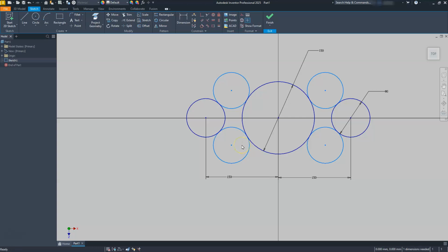Okay, finally, I can use my trim, so just a T. I'm sorry, it's X actually in this command. So I can use the X, and that'll put me into the trim mode, or select the icon that is located here. And then the last thing I need to do is go ahead and put a radius on here. So I'll go to my dimension, select here, and this has a radius of 100. All right, so all of these should appear and look correct.